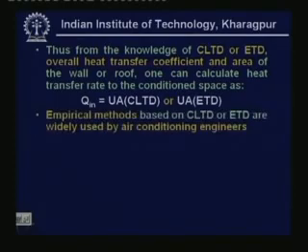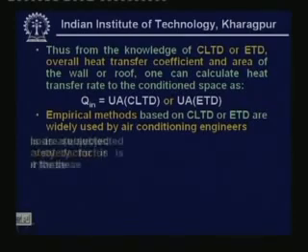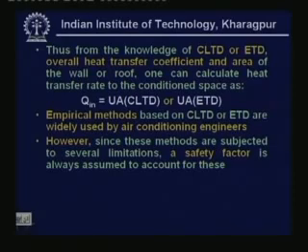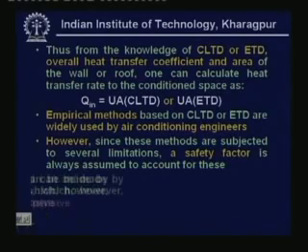Okay. Now the empirical methods based on CLTD or ETD are widely used by air conditioning engineers. However, since these methods are subjected to several limitations, a safety factor is always assumed to account for these. Okay, so they are not 100% accurate, all these empirical methods. So to take care of this, a safety factor is always assumed.